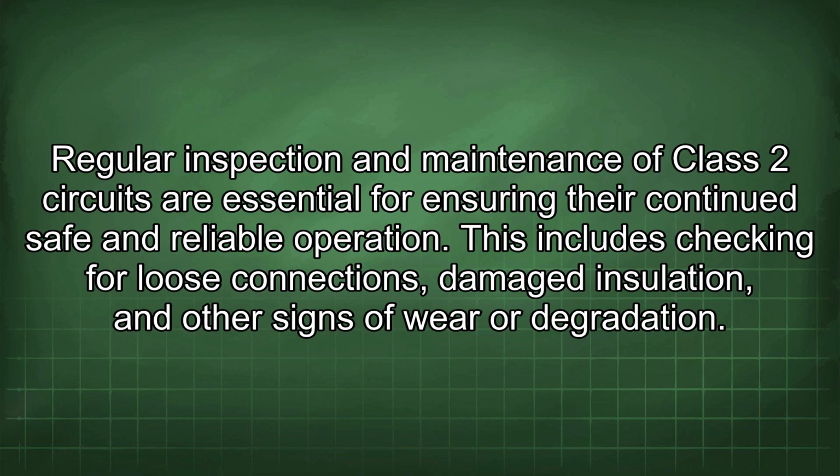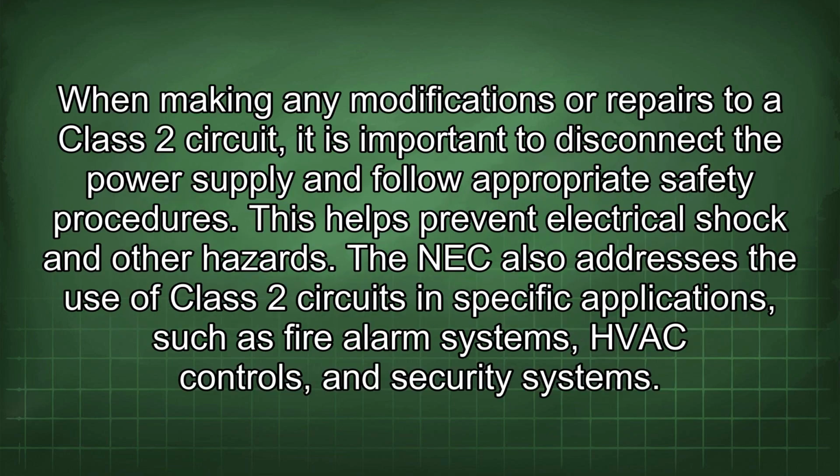This includes checking for loose connections, damaged insulation, and other signs of wear or degradation. When making any modifications or repairs to a Class 2 circuit, it is important to disconnect the power supply and follow appropriate safety procedures. This helps prevent electrical shock and other hazards.